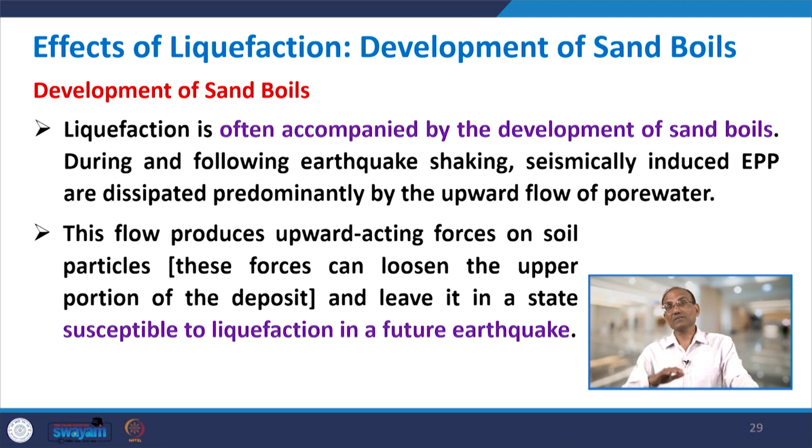Now, the second part, the second step, is related to the effects of liquefaction: development of sand boils. Liquefaction is often accompanied by the development of sand boils, which have been observed during many past earthquakes. During and following earthquake shaking, seismically induced excess pore water pressures are dissipated predominantly by the upward flow of pore water. In the case of development of sand boils, the excess pore pressure flows upward and then comes out.